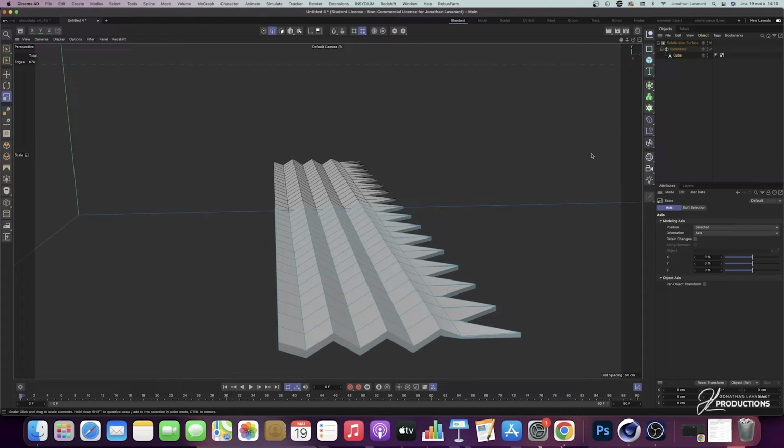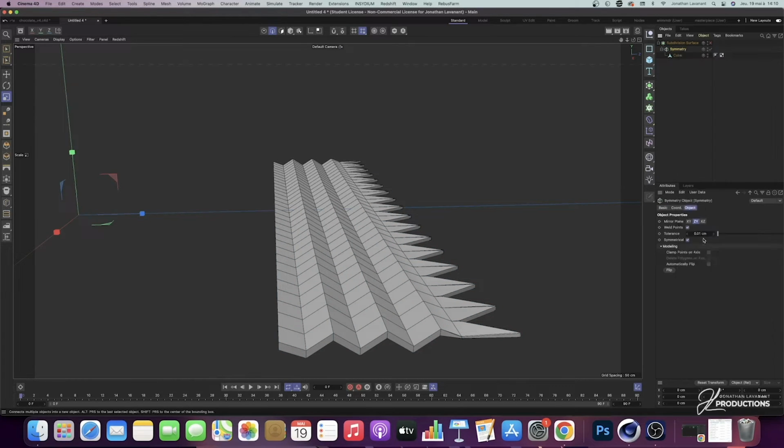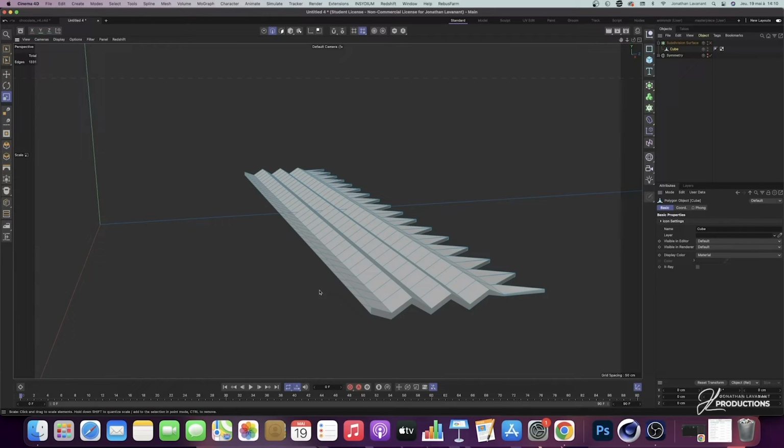So there, before continuing, we are going to apply the symmetry here. I have selected my object well, and I'm going to make the right side connected, and this one I'm going to deactivate temporarily. We keep it as a backup if ever we need it. So there, I'm going to double click with Alt to temporarily delete it. I will put here and there. So we have our object that has merged with symmetry.